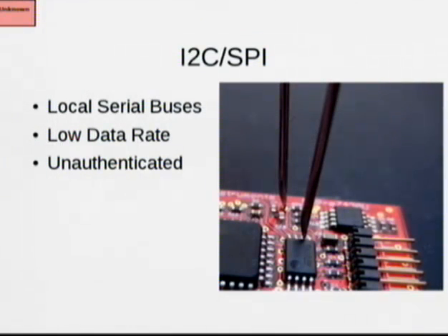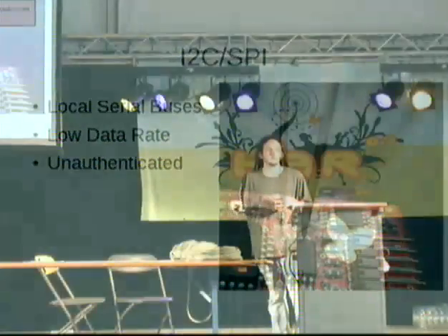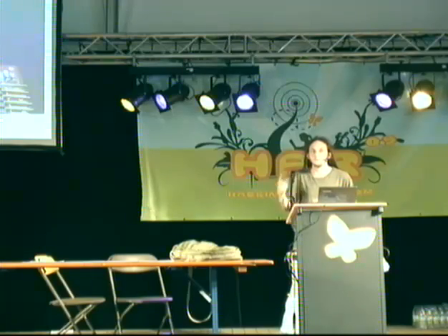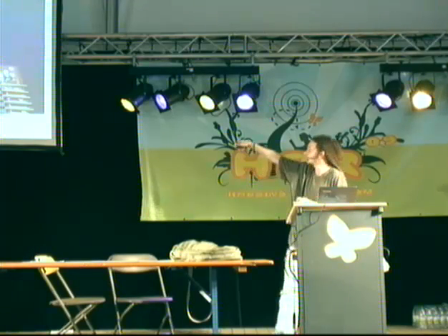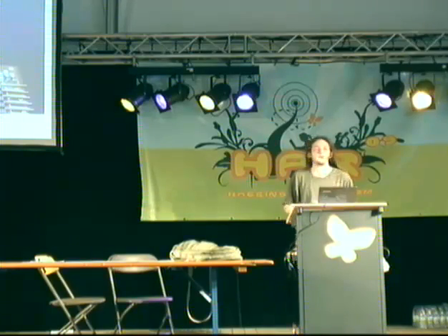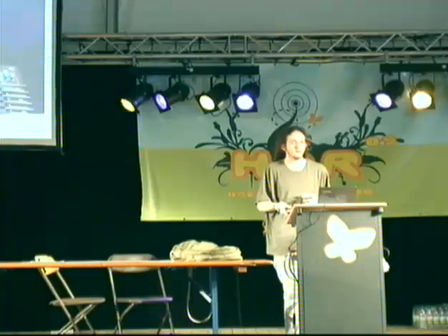And these 2 are connected by an I2C bus, which is multi-master. And because it's multi-master, unless one of these chips is trying to hold the line open, you can connect to it as a second master, and you can just ask the memory chip for its contents while the board is still running. So in this case, I dumped the firmware that was contained within this memory chip just by tapping the 2 right pins on the top and having a regular I2C ROM programmer. You just run the commands out, you say, I'd like a contents of memory, please, and it gives it to you.